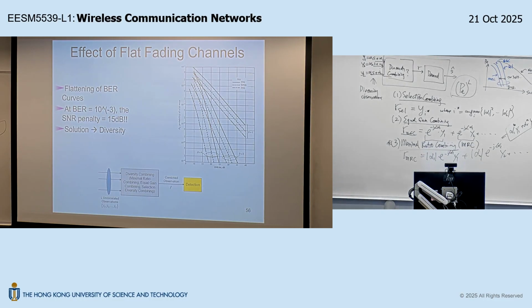By partitioning this into two halves, compared to without partitioning, the signal to noise ratio of this alpha hat will be 3 dB worse, right? So if you continue to partition into four pieces, then this quality will be 6 dB worse. Eventually, if you keep on doing this, this alpha hat will be so unreliable that it is not related to the actual alpha.